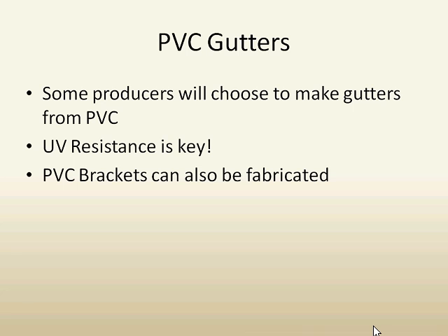If you don't do that, what's going to happen is that your PVC is going to degrade. It won't be but a very few years, and your PVC will get brittle. So you definitely want UV resistance. I've included in the handouts a PVC bracket that can be fabricated for holding up a PVC gutter.